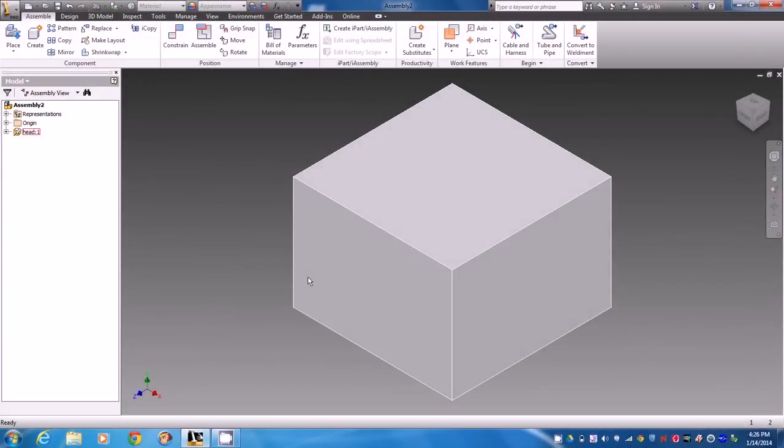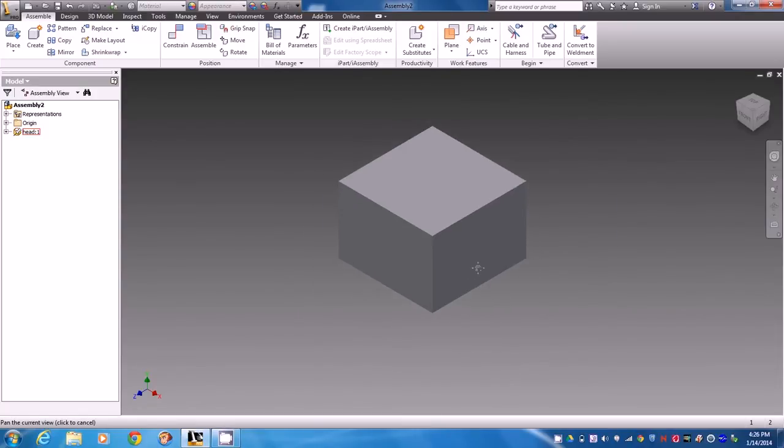This video will show you how to assemble your CubeeCraft after you've created the shapes. So I'm going to go through and assemble it. I've got a new assembly file here. I've got the head placed inside the assembly file. Remember that since that's the first part that's inserted, that is grounded, as you can see over in the browser.